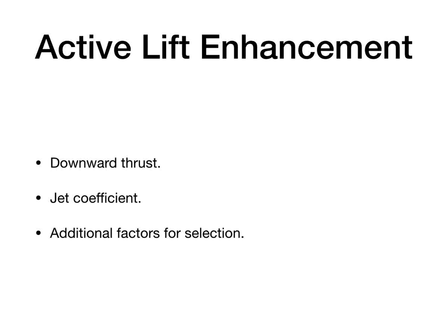In addition to the enhanced aerodynamic lift that these three approaches provide, they also generate a component of downward thrust. This results because of the Coanda effect, which is the ability of an air stream to follow a curved surface. When properly designed, the airstream on the upper surface leaves the trailing edge at the angle of the flaps.